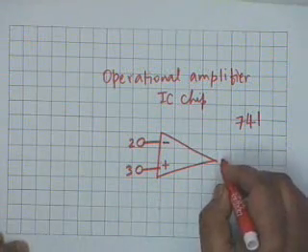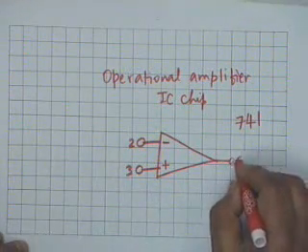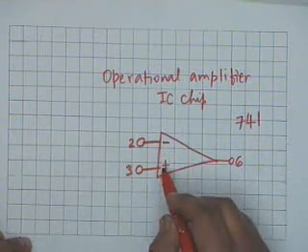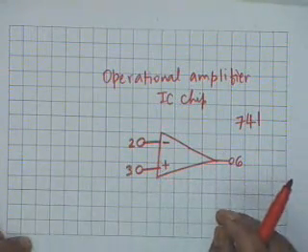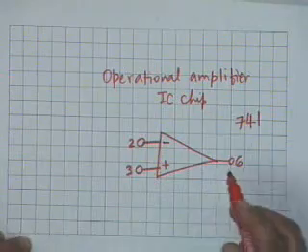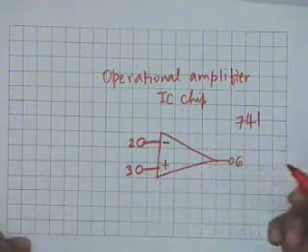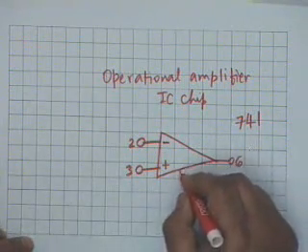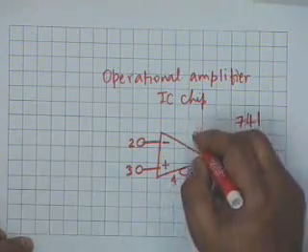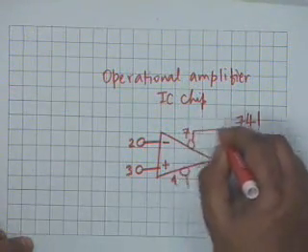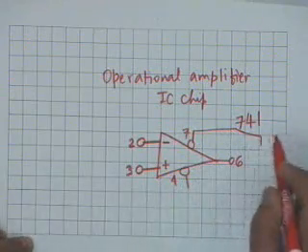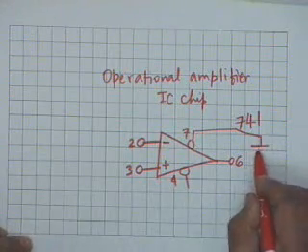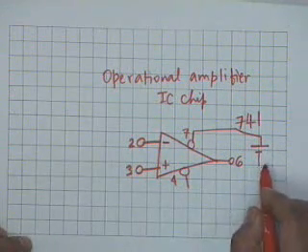All right. The output terminal is the terminal number 6. There are 2 inputs, 1 output. You require other terminals for power supply connection. Any electronic circuit requires a power supply, a DC battery to be connected, and the power supply terminals are 4 and 7. The typical 741 requires a power supply of 2 kinds of polarities, that is a positive one as well as a negative one.